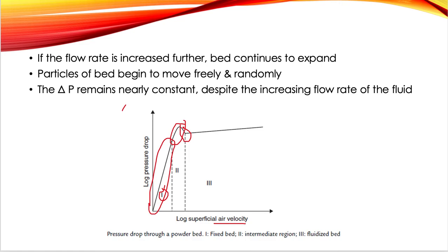So in this condition, it will look like the bed is being boiled, or we call this boiling beds or discontinuous fluidization. And then when particles are actually dragged, two-phase circulation occurs. This is what we call continuous fluidization, and continuous fluidization is the basis for pneumatic transport.